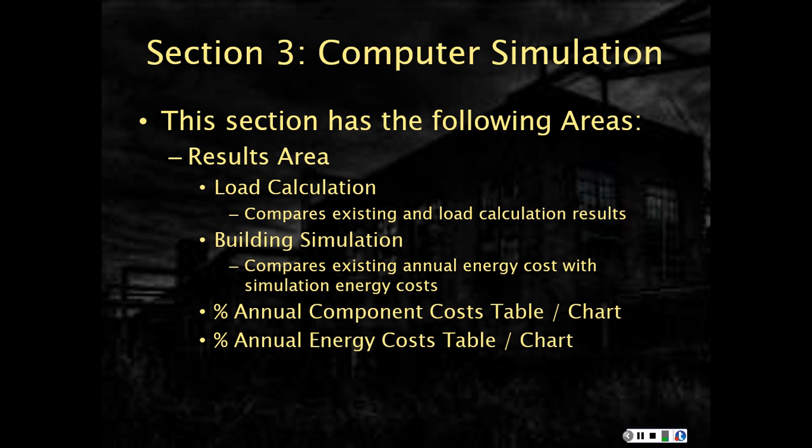So back to the load calculation, when I compare that, I really have a table of existing equipment, including their current heating size and cooling size, cooling in tons, heating in BTUs, and the carrier program will predict a recommended sizing, and we plug that in. So we put cooling in tons, heating in BTUs, and we compare the two. If they're too far out of sync, this would generate recommendations for later on in the document.